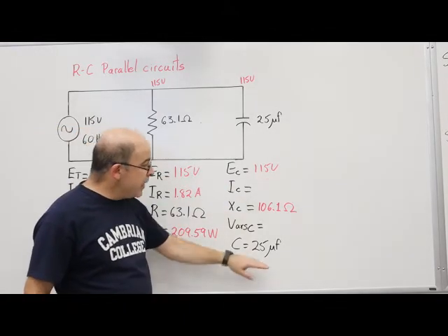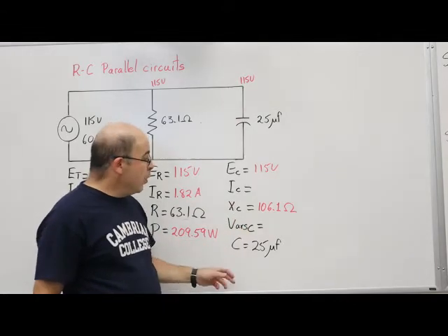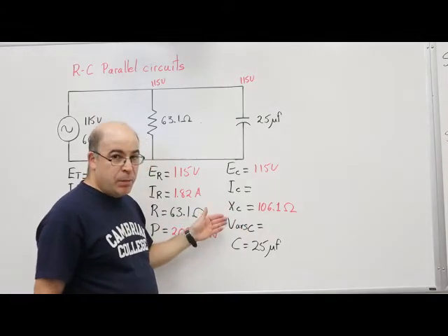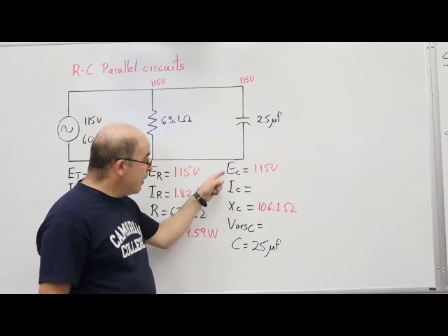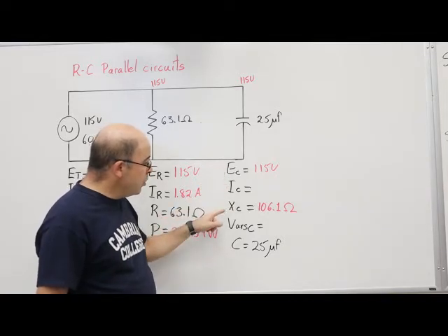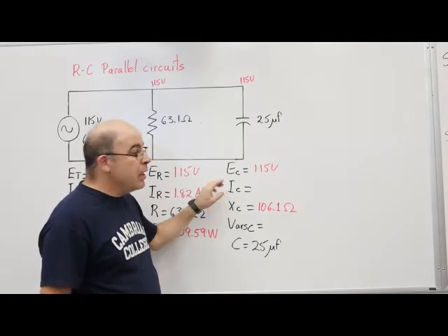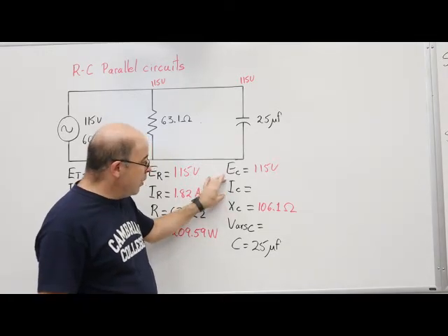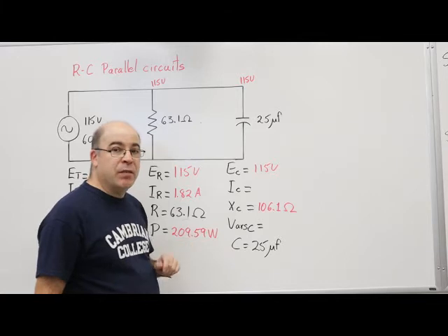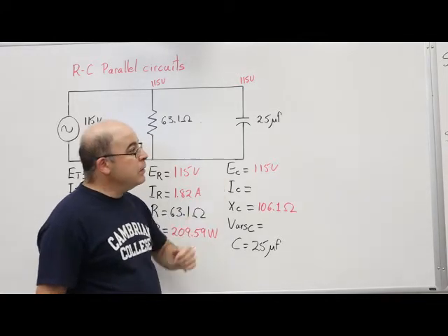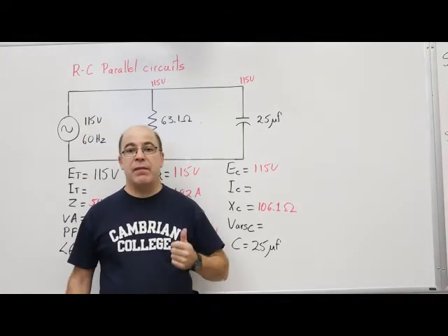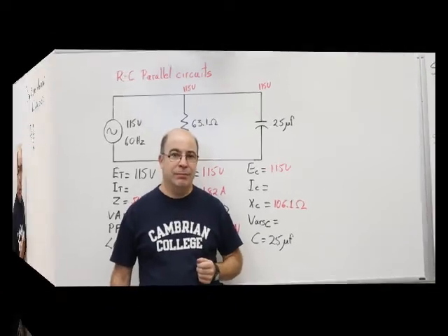I've got the remaining branch, the capacitive branch, where I'm going to basically repeat the exact same thing. I'm going to use the voltage and the capacitive reactance to calculate the current draw. Using this value, it'll allow me to calculate the amount of reactive power. So I'm going to move down, and we're going to be doing steps 5 and 6 consecutively.